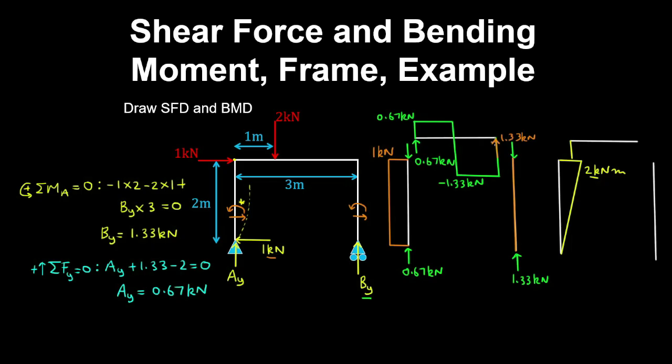Now on the other side, we saw that the beam had 1.33 kilonewtons acting on it, so 1.33 by the moment arm, which is 2 meters up to the point load. So that gives 2.66 kilonewton meters where the point load is. And the bending moment diagram is piecewise linear in that beam because there's only a point load acting on it. And you can also observe that there's no horizontal reaction in the roller, so therefore the bending moment in that column is 0.